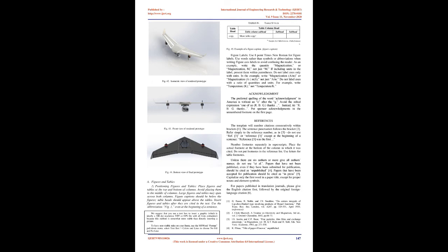G. Ingress and egress mechanism. 1. Launching. The wing can be launched by hand or can be launched using a bungee catapult launcher during takeoff. 2. Ingress/egress mechanism. The flying wing has open wingtips, and the wing has an inner cavity. The wing acts as a ballast tank. When the wing has to traverse underwater, it first has to land on the water surface. Water enters the wing through the open wingtip and fills up the wing.